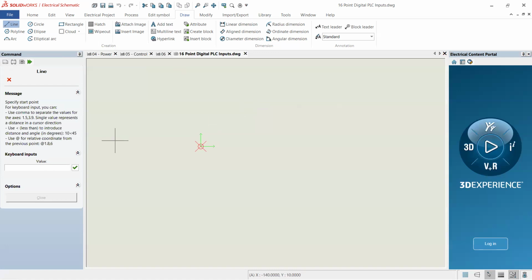So we get a pop-up. I can either start drawing and it'll snap to 0, 0. That's fine. I like to use the input over here on the left and actually type 0, comma 0. Enter now in my line. Notice it starts now at 0. No questions. I like to sort of draw down. So in AutoCAD, this actually takes AutoCAD input as well, this field. So now the 0, 0 I just typed,